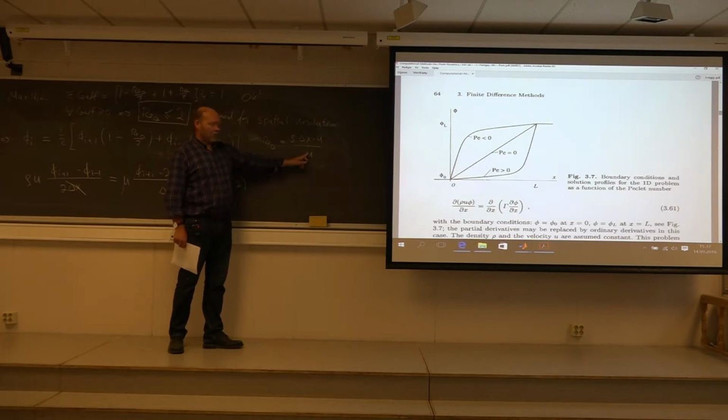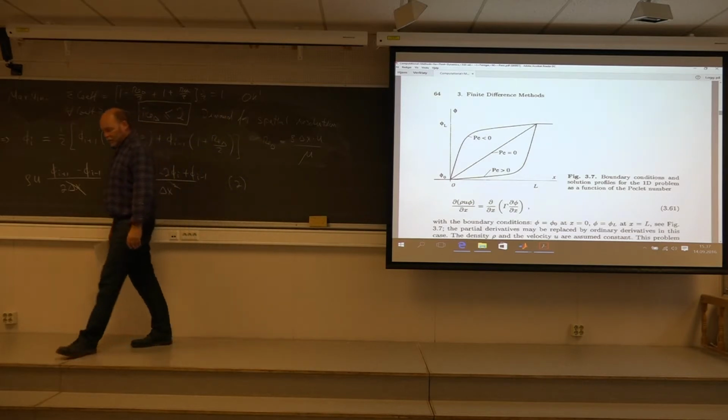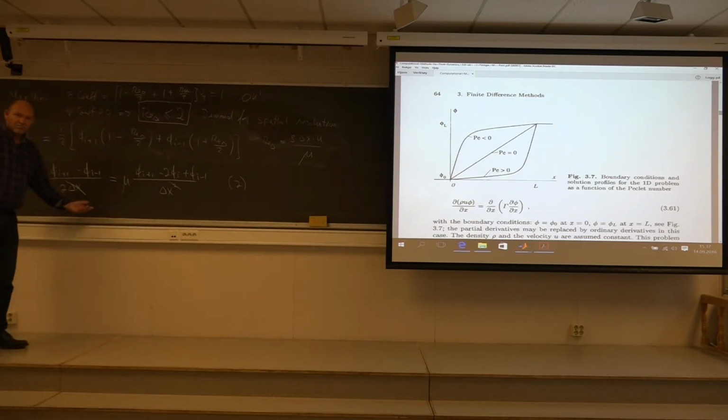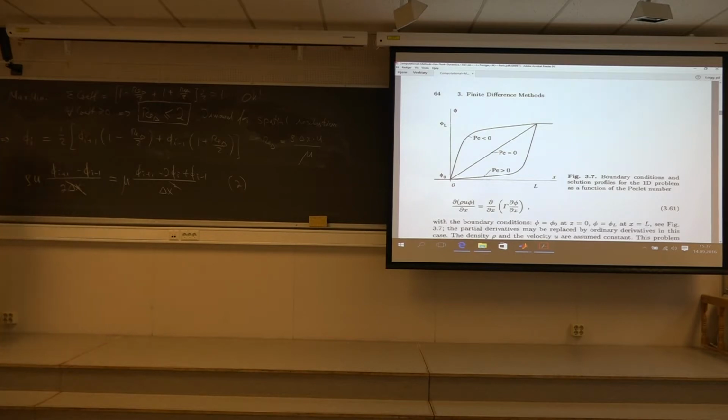This viscosity here can be very small indeed, so this can easily be a big number. Delta x can be very small, that's your choice, but can come down to millimeters, micrometers. How small do you have to go to get this criterion? It can be tough. So this is something we have problems with, yes. But the demand is there, so it's quite unquestionable.